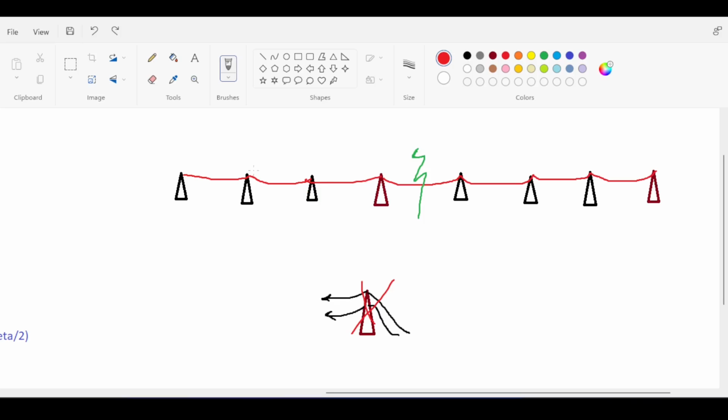Now, this is totally normal. You would think, wait, if we know about failure containment, why do we still see consecutive failure in towers? Well, you see, you don't design all your towers to contain the failure. However, you select a few towers to be ready for such a case of failure. So it's actually more economically feasible to design some towers to act as failure containment towers and leave the rest to not contain the failure.